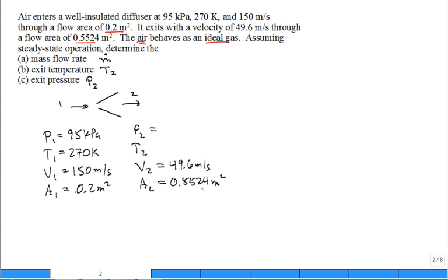Now, this is a made-up problem. And when you see a number like the area 2 to 4 significant digits, something's going on. Let me just tell you what's going on in the background. I made this problem up and made sure it was physically possible so it didn't violate the second law of thermodynamics. And so this is frictionless flow. This is inviscid flow through this diffuser. It's isentropic flow. You may not understand all those terms, but by the end of the semester we will. It's reversible flow through that diffuser. So there are limitations that come from the second law, and this one is a great diffuser. But to make things work, I basically had to go in and pick the 4 significant digits for that area, and that velocity is 3 significant digits. I didn't want to make a problem that violated the second law of thermodynamics. That would be bad.